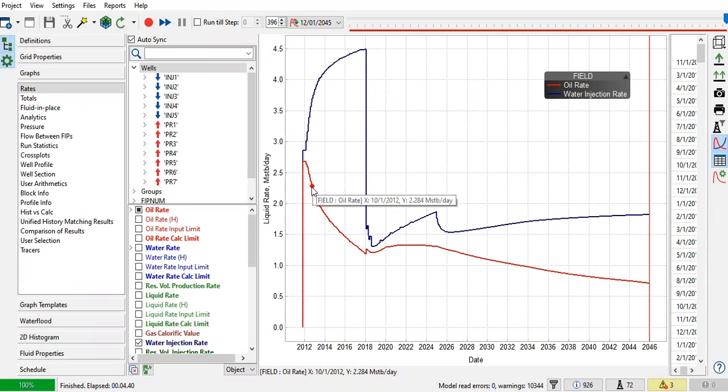So here we have fast or rapid production decline, but after we inject polymer in 2018 and we improve the concentration of the polymer in the end of 2024, first we have production increase, and maybe you can say that the decline is being mild here. So we arrest the production decline.